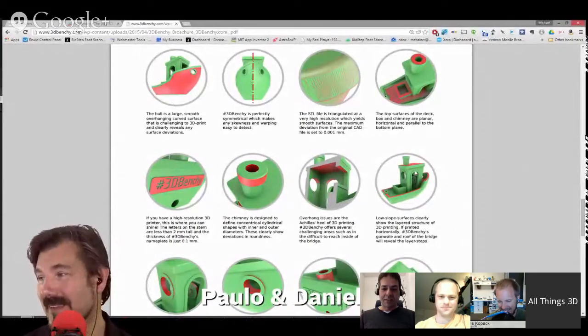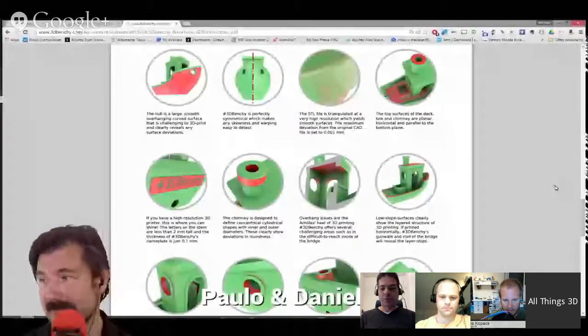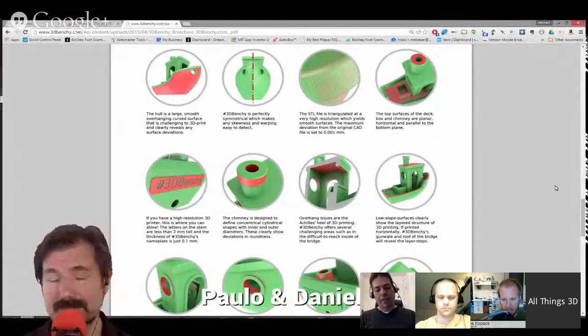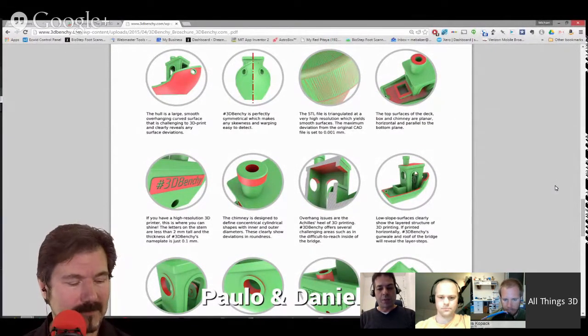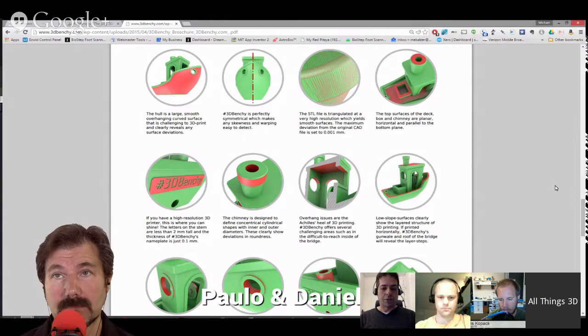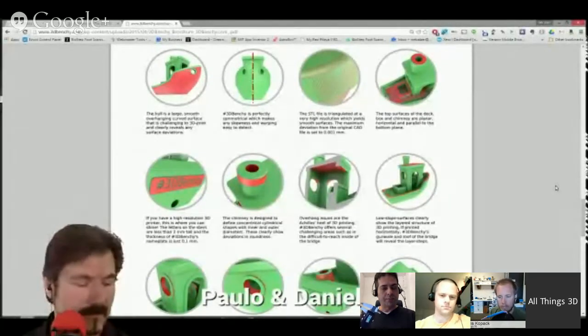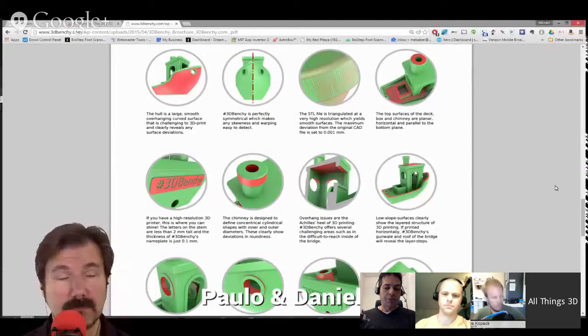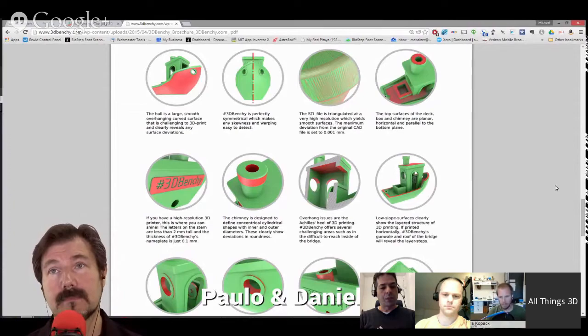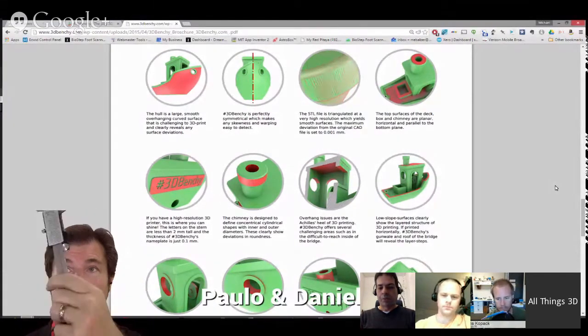The chimney is a cylindrical shape, which is perfect for putting your calipers on and measuring how round things get. If your belts aren't correctly tensioned, this is what you will see on the chimney. And I would actually recommend anyone who wants to get into measuring, get digital calipers, they are good, but get one with a clock, you know, that looks analog, with a visor.